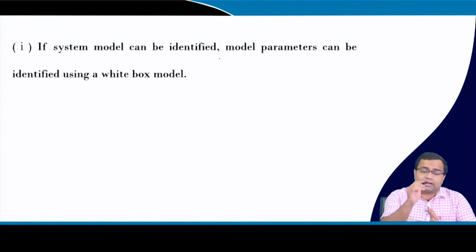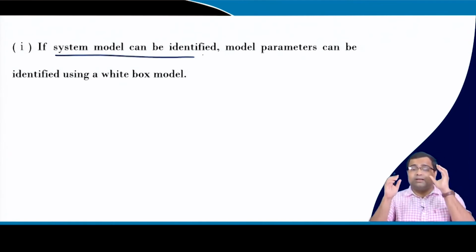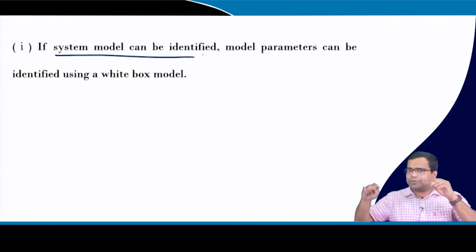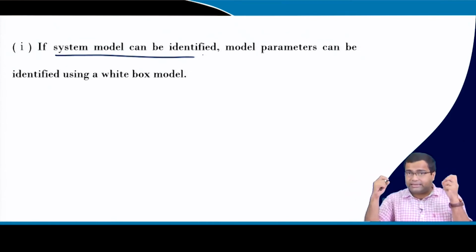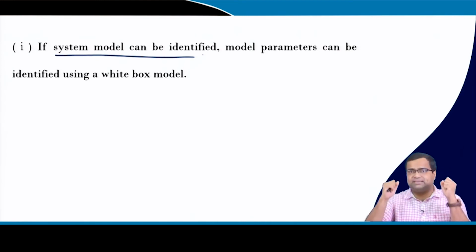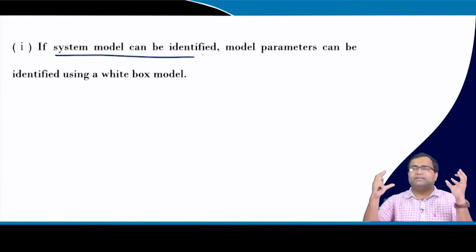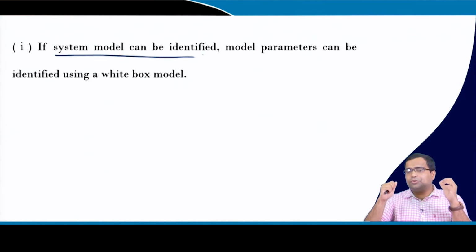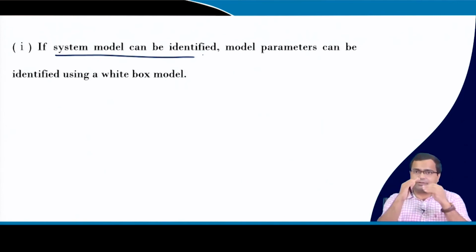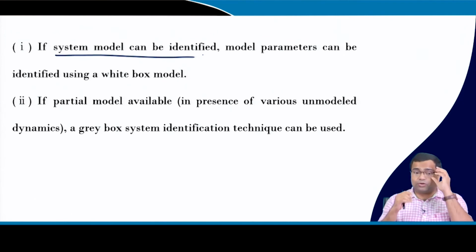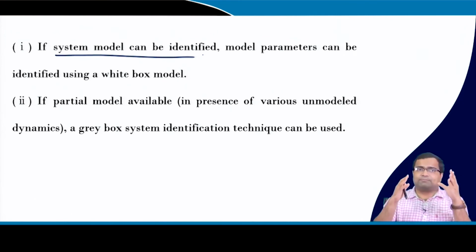Now it may so happen, whatever model, that you did a practical test of a converter and you try to derive it, because nothing is known inside the converter except the inductor and capacitor. So we need to obtain the closed loop output impedance expression. We may not be able to model everything. From the measured response, if we want to match, and we have some information about the converter, for example in the buck converter, we know on the output side there is an inductor and capacitor, so we know the circuit and can derive the model and try to match. That is the white box model.